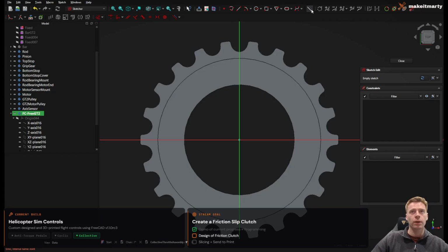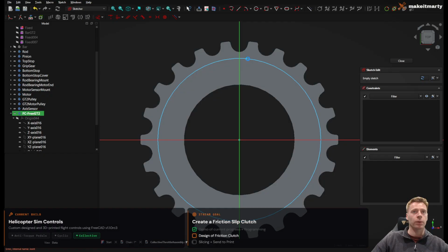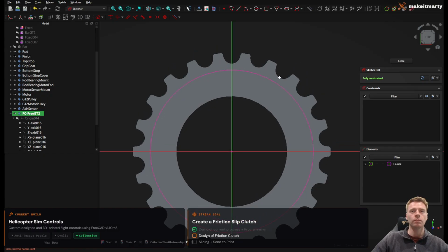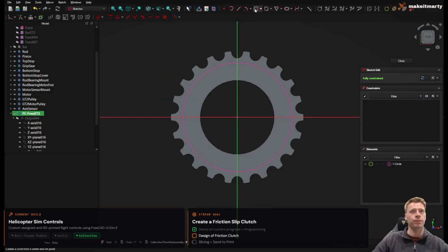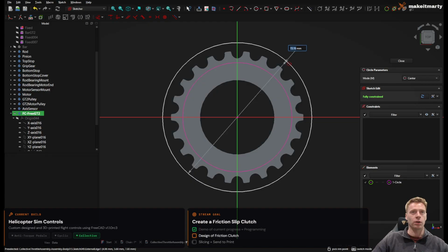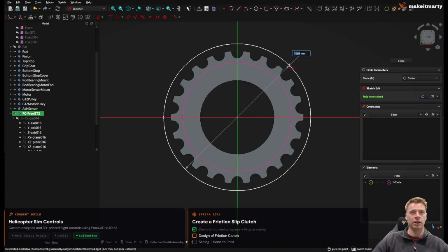So we are going to take the external projection tool, and we're going to select that there. And that's going to be our internal projection, or the internal part of our wall. And then we're going to do something like, let's say 15. That looks sensible there.